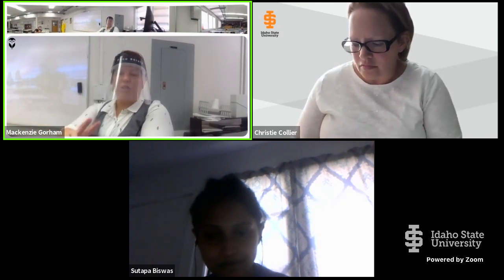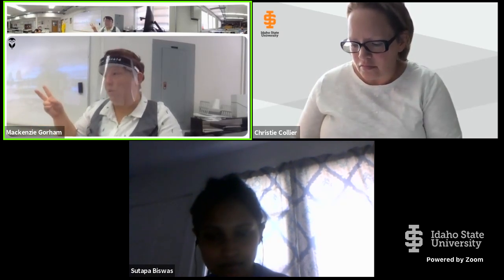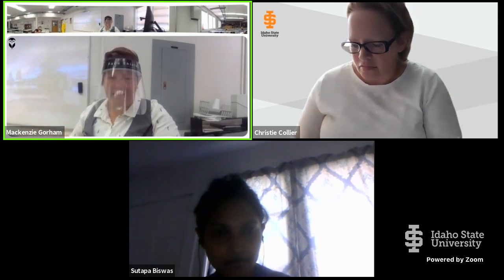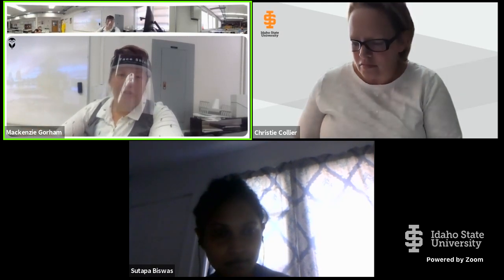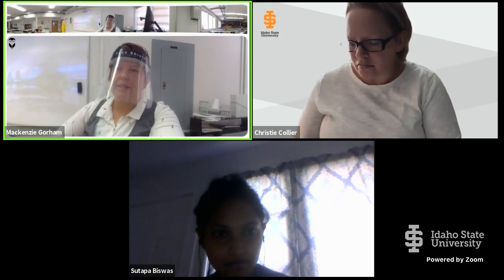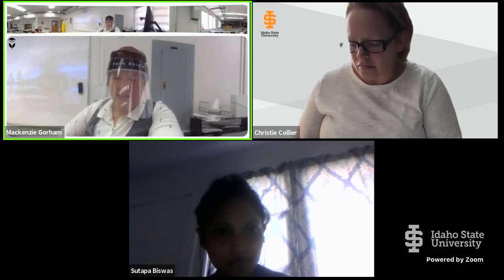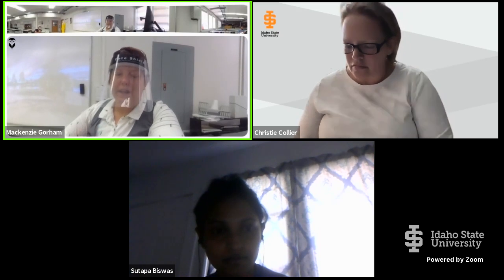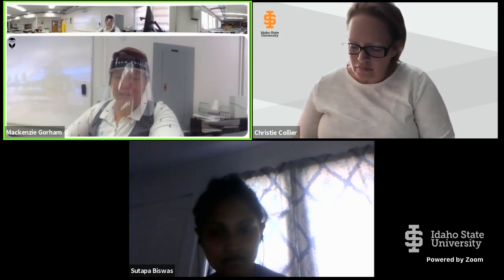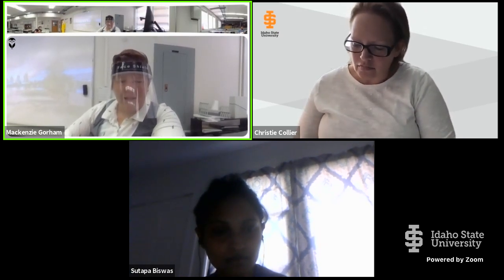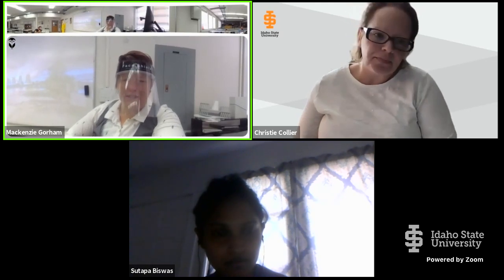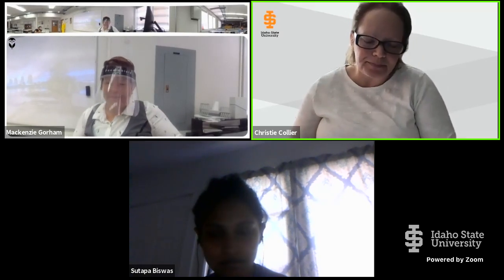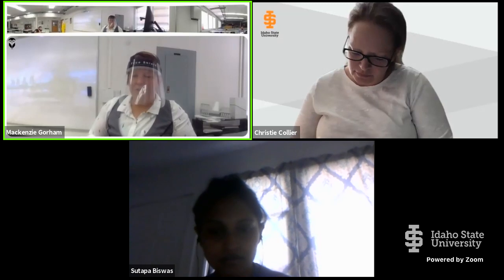And even with only 2 of them, the 2 least worth, we're still fully shut down. That's our stuck rod criteria. So it's not that one of the rods is specifically a stuck rod. It's that whichever one is highest worth, we have to not count it per our stuck rod criteria. Does that clarify for you? Yeah. Okay. Awesome. Sue, any questions?